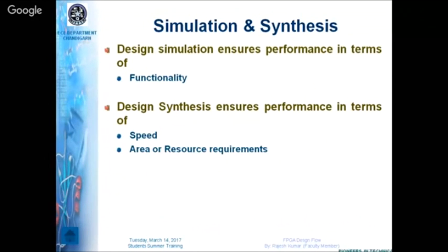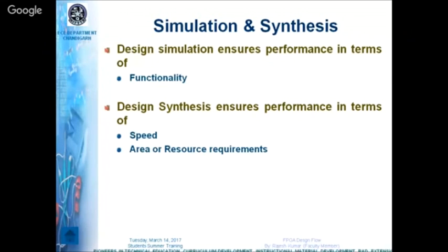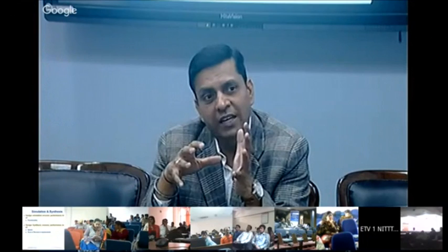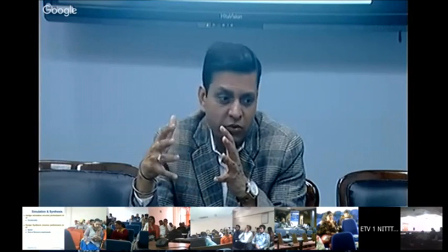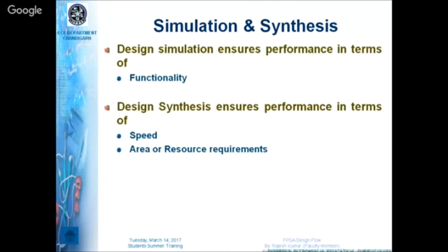Then the second point was simulation, and here again, you are going to simulate your design in two phases. First you are going to create your M code, and you are designing your filter in M code and simulating it. Then MATLAB is giving you filter order and different coefficients. You are going to take those values from MATLAB, use those values in your HDL, and develop your VHDL code or Verilog code, and again you are going to check the functionality.